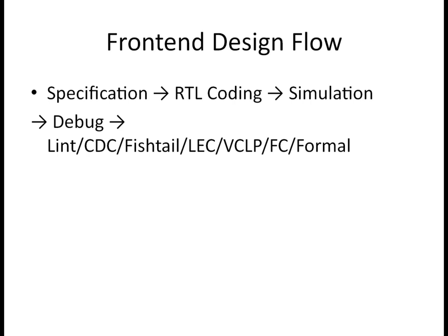Let us segregate these into two different techniques: one is single-bit synchronizer, and one is multi-bit synchronizer. Even in single-bit synchronizers, there are different techniques: two flop synchronizer, three flop synchronizer, toggle synchronizer for pulses, handshake-based synchronizer, and so on.